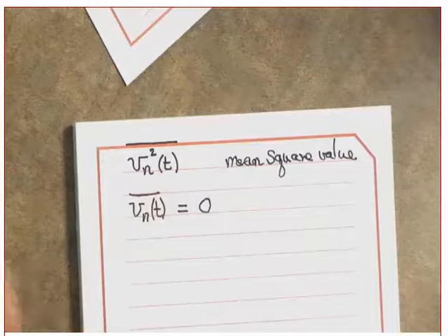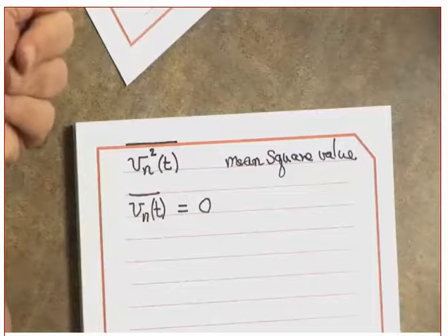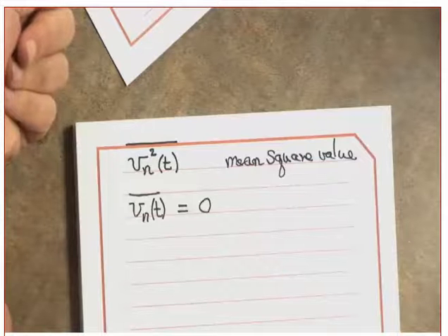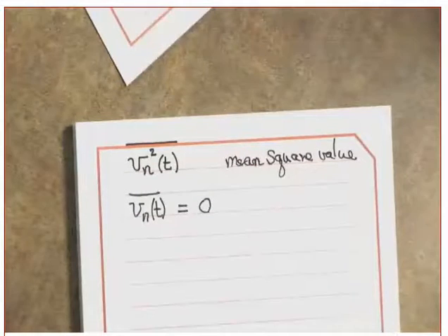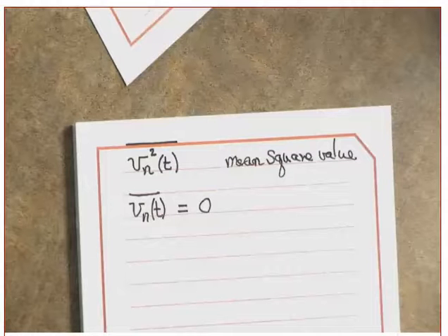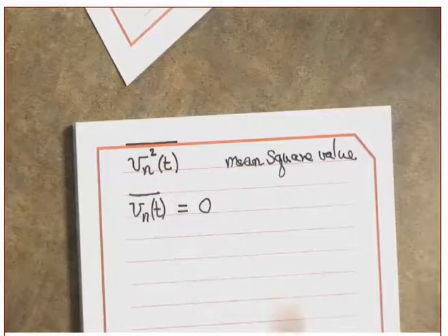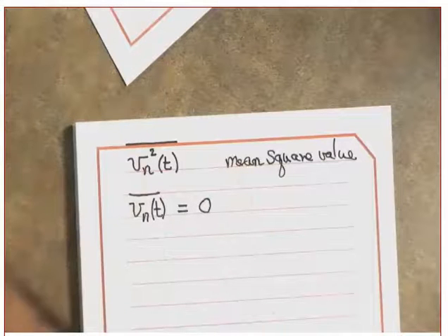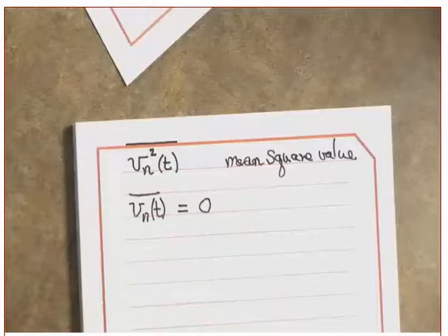Why is it a very fast fluctuation in time? What did the power spectral density of the noise look like? It looks constant for all frequencies, which means high frequencies are there. So when you look at it on the oscilloscope, which is the time domain description, you will see some of it positive and some of it negative. What is the average?